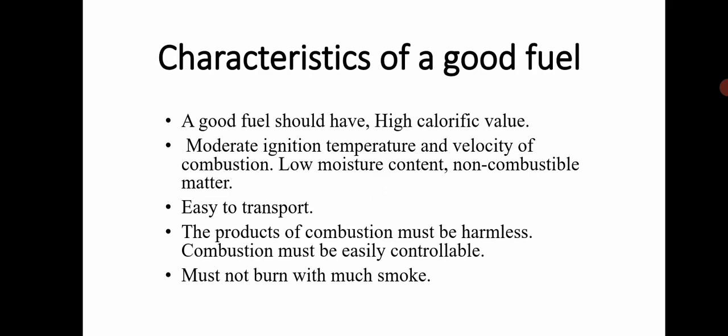Now we discuss the characteristics of a good fuel. A good fuel should have a high calorific value. It should have a moderate ignition temperature and velocity of combustion. It should have very low moisture content and non-combustible matter. It should have low volatile matter also. It contains high carbon content, and it must produce a high calorific value.